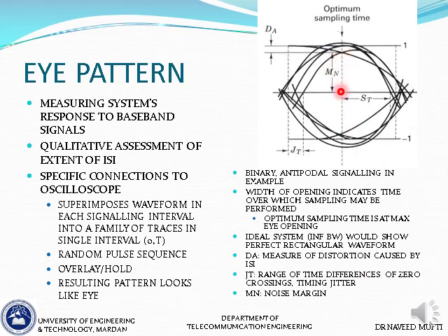This is our noise margin, from the center of the eye, from the center between these two levels, to this point here. This is our noise margin. So as you can see, the distortion caused by ISI increases, and that decreases our margin.